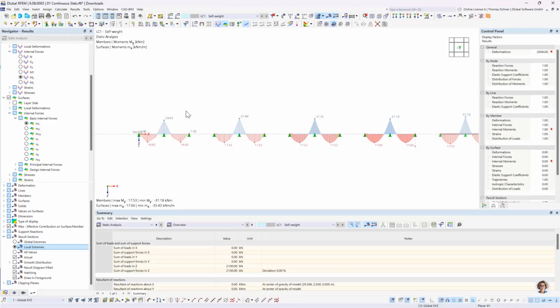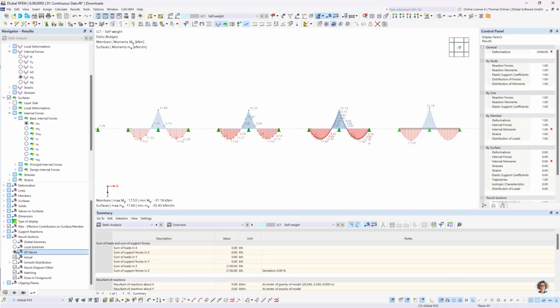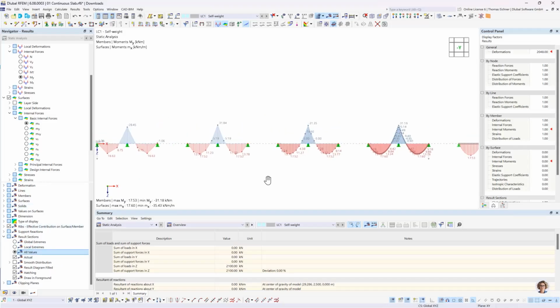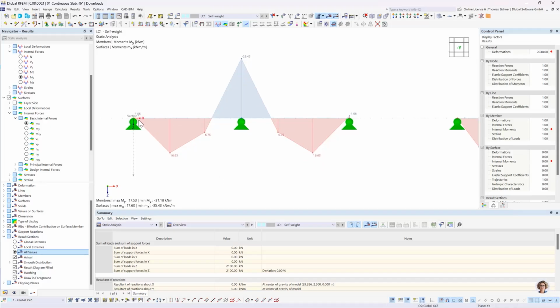On the other hand, let's look at this extremely fine mesh, and let's also show all values again. Within the left system, we only have 1, 2, 3, 4, 5, 6 elements here. So our global stiffness matrix is constructed out of the element matrices of 6 elements.